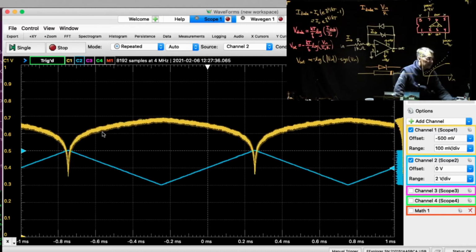And then because of that logarithmic behavior, as the argument gets bigger and bigger, the slope of the logarithm function gets smaller. So this is this flat portion here. And again, we call this the barn roof distortion. So it kind of looks like a barn roof or a gambrel style roof. And then down here, where the input signal is small in magnitude, the slope of the logarithm function is quite big. Again, this is like the sides of that barn roof. So the top of the barn roof, the sides of the barn roof.